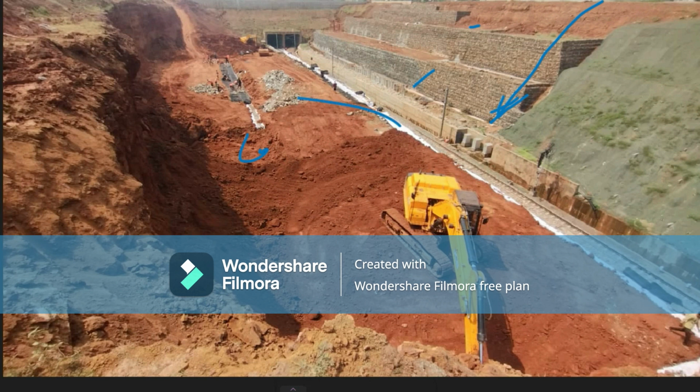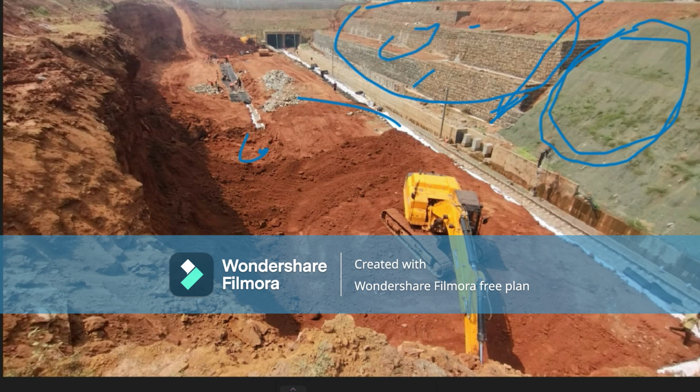Here is the turfing geomat, a high performance turf reinforced geomat with geomesh. They constructed it to prevent soil erosion and to stabilize the slope against rain water. The existing slope has not failed, but in this area soil slope failure happened. For this reason, they again constructed the gabion wall, a retaining wall.